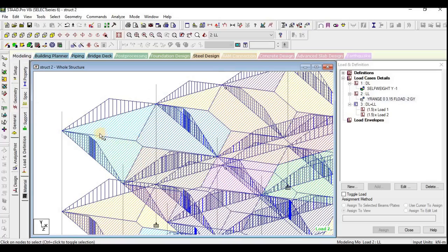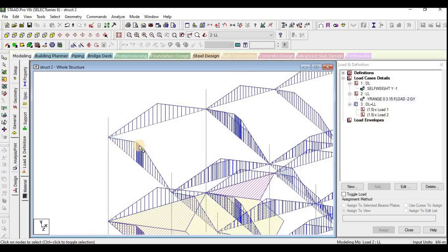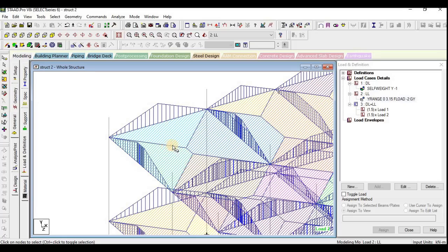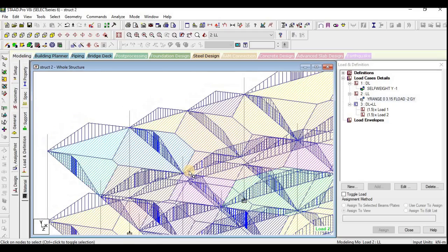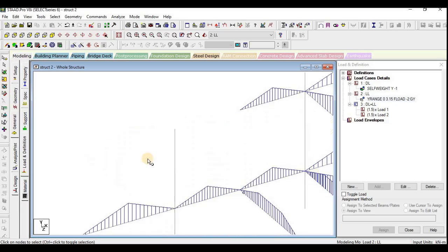Okay, that is crack pattern. It depends upon the crack pattern of the slab. Yield line theory, we may have studied about yield line theory. In yield line theory, the load will be transferred as trapezoidal and triangle in a rectangular slab, and 4 triangles in the square slab. That is the concept we are studying in yield line theory.